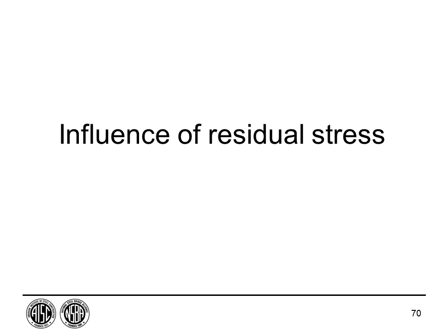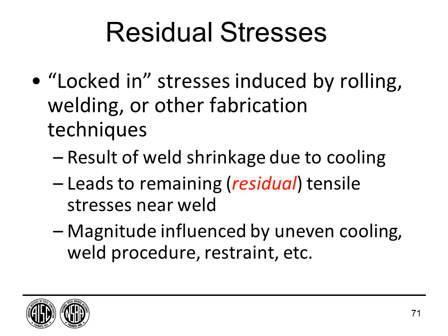These are the locked-in stresses that occur in a structure. How do they get there? Well, if you've ever been to a steel mill and you see the steel rolling and it's hot, it cools unequally, so there's stresses because it cools unequally. The process of welding introduces a lot of residual stresses. Again, they're not bad, they're accounted for, but they're there, as well as other things we do in fabrication that lock stresses in. Primarily what we worry about, though, is weld shrinkage due to cooling.